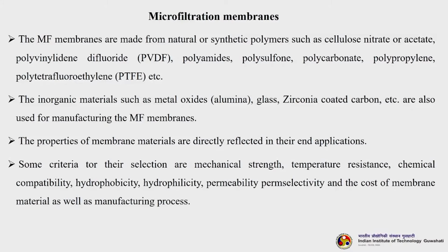So, microfiltration membranes are made from natural or synthetic polymers such as cellulose nitrate, acetate, PVDF, polyamides, polysulfone, polycarbonate, polypropylene, PTFE, polytetrafluoroethylene. Inorganic materials such as metal oxides like alumina, glass, zirconia, coated carbon etc. are also used for manufacturing the microfiltration membranes.